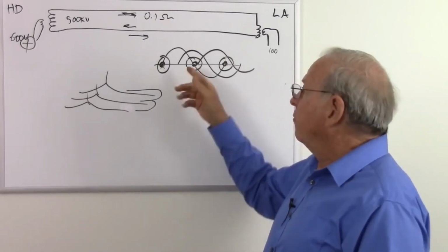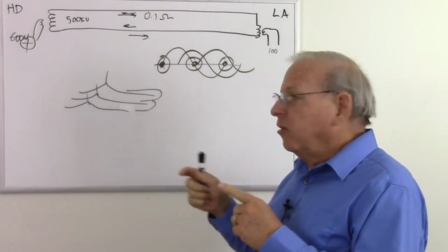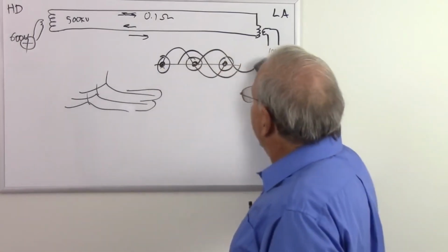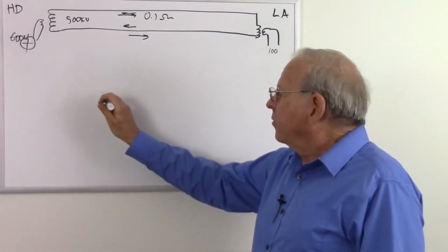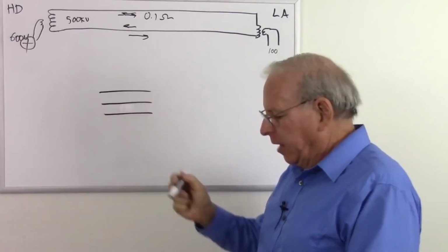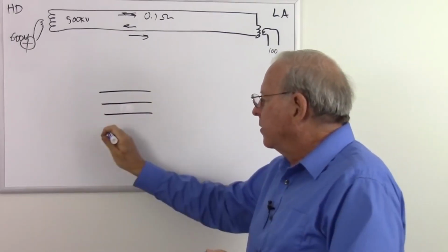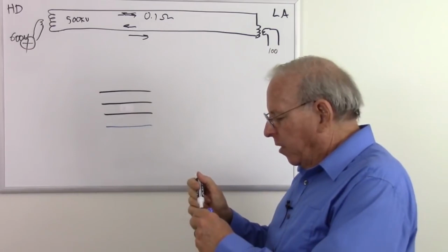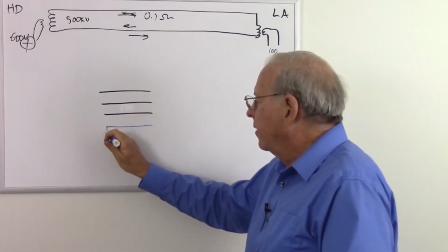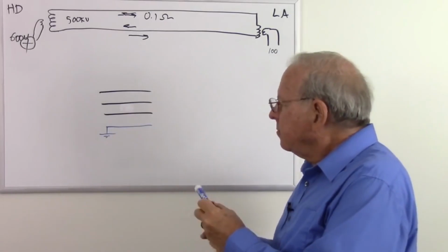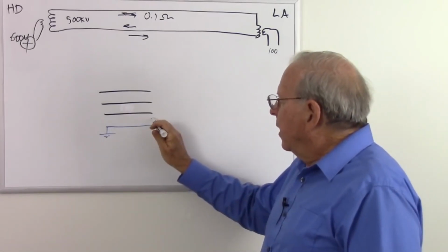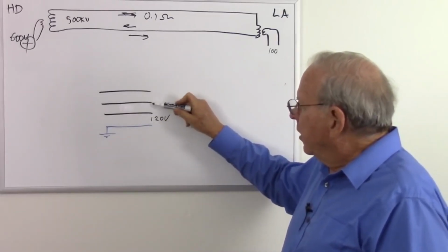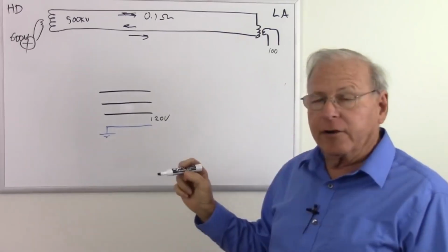So industrial motors will be 3-phase motors, and so they will send all 3 of those phases to industrial areas to deliver to those 3-phase motors. Now when they deliver those 3 phases to an industrial area, there's the 3 phases and the ground, they'll step that voltage down so that the voltage between any one of these phases and our neutral wire, which of course once again is grounded somewhere to reference everything to ground, that's going to be 120 volts. So between this phase and ground, 120, that phase and ground, 120, that phase and ground, 120.